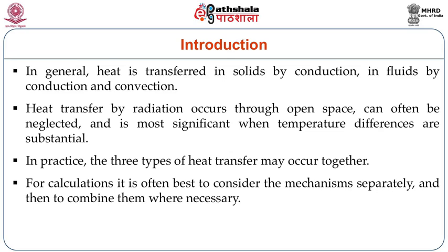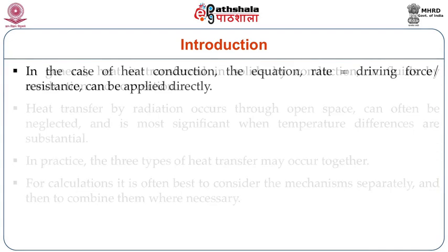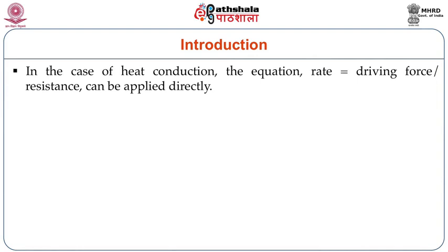For calculations, it is often best to consider the mechanisms separately and then to combine whenever there is a necessity. In case of heat conduction, the equation will be rate is equal to driving force divided by resistance. This can be applied directly.